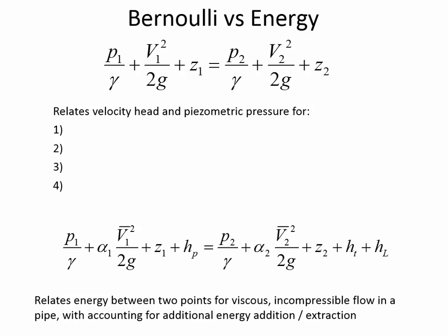So you'll notice here it says H sub P. Over here it says H sub T, which means turbine. And then there's also this other term, H sub L, which is head loss. And so now there's an important directional component. What we assume for the energy equation is that water is flowing from 1 towards 2. All you have to do to get water to flow from one point to another is just to write 1 upstream and 2 downstream. And that's the magical power that makes water flow. Okay? Not really, but that is the convention that we'll use, that 1 is upstream, meaning that that's where the water's coming from, and 2 is downstream, meaning that that's where the water is going to.